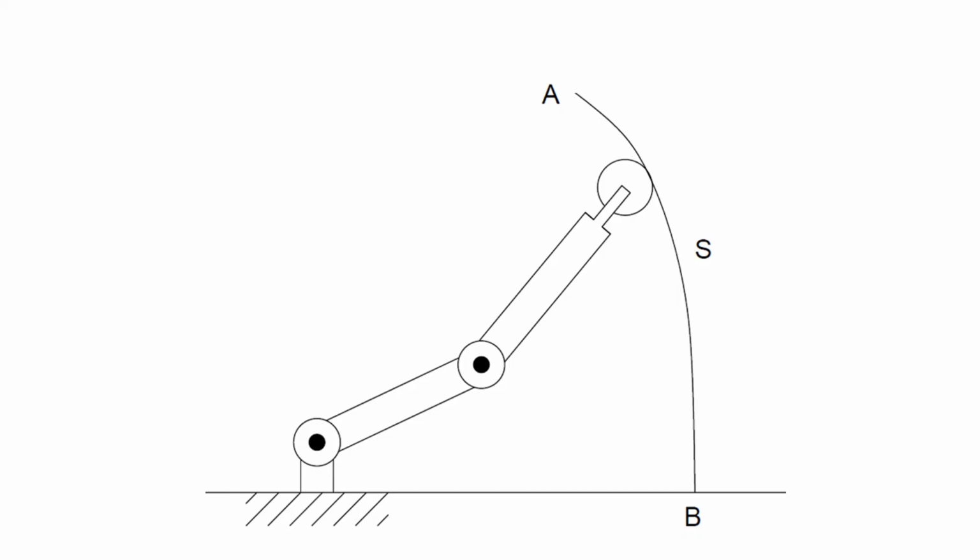In a robotic manipulator, you are going to have joints. These joints are going to have motors in them. So this is going to be a joint. This joint is going to receive the information from the controller, and it is going to produce an output. Output generally, because it is a revolute joint, is going to be in terms of theta, for example. This theta needs to be picked up or measured using some sort of sensor, probably an encoder, which is going to provide this signal back to the controller.